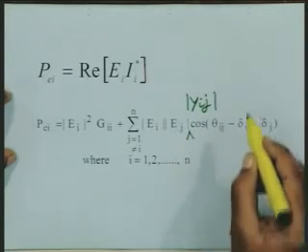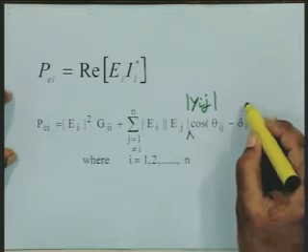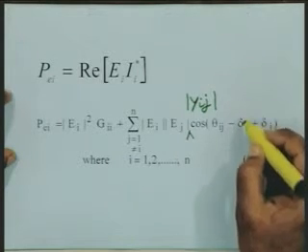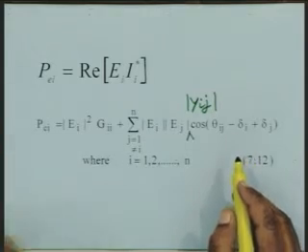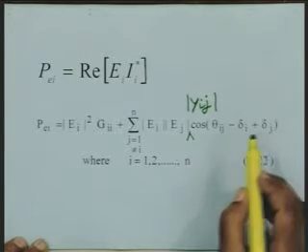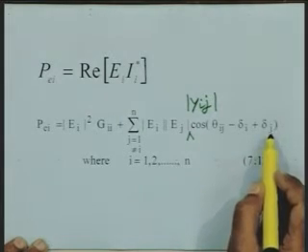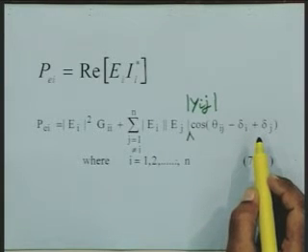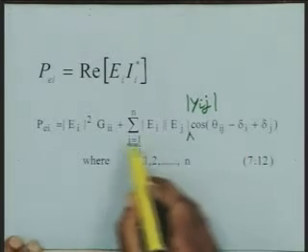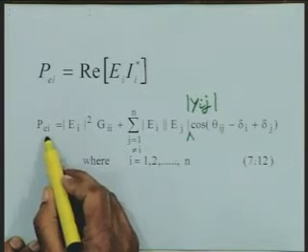The only things which are not known are the quantities which vary, the delta i, delta j. Therefore, these angles will be computed by using a numerical technique, and at the end of each step of computation these angles will be known. Therefore, we substitute the values of these angles, which are computed when you solve the swing equations, and you get the expression for PEi at each step.